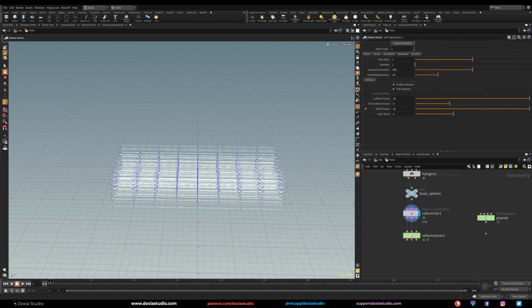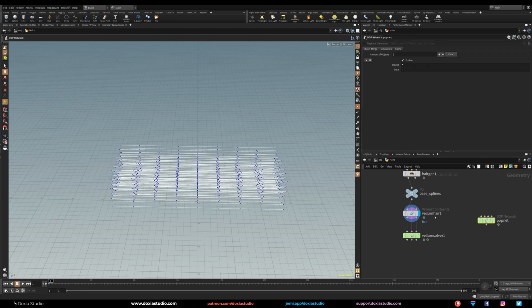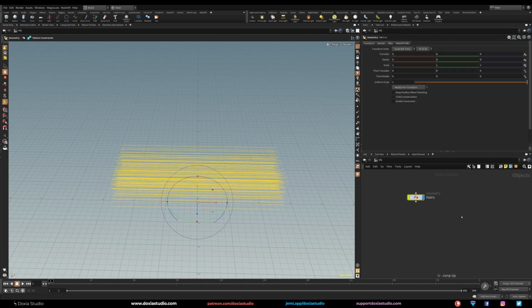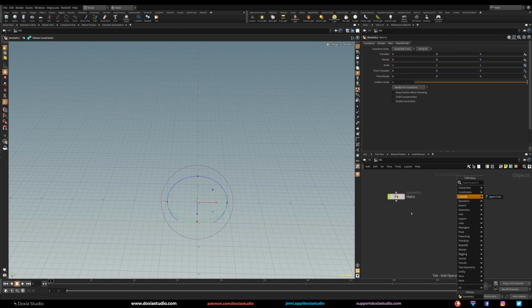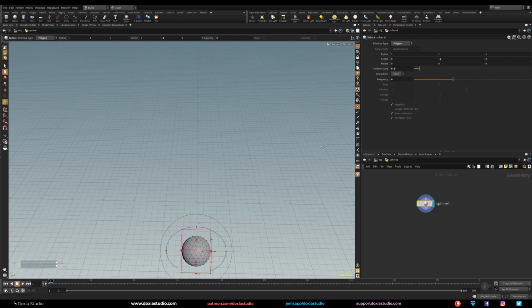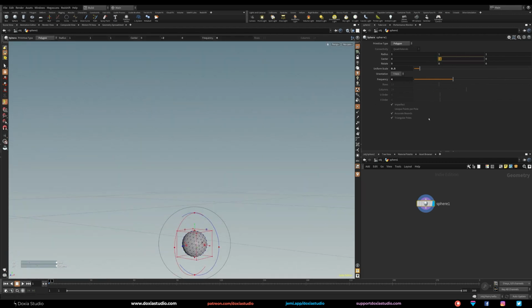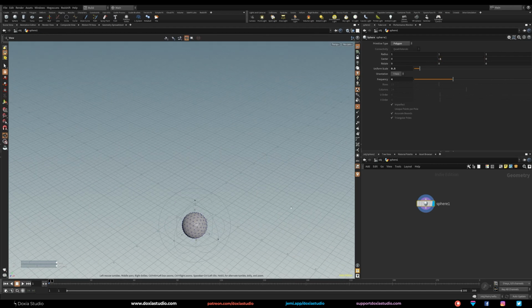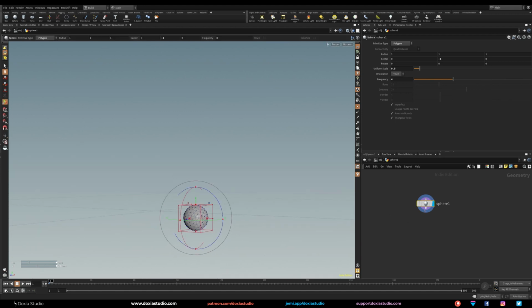So in our case, we are going to use a pyro simulation to affect our hairs, okay? And create this cool and fluid animation. So let's for now go up. Let's turn off our hairs and let's create our pyro simulation. So let's go really quickly. I'm not going to explain that much here because I already covered this in the intro to pyro simulation. Let's lower this down. Let's change to polygon, change the frequency. Let's put this down a little bit. Maybe -1. Because I want this to be below the floor, okay, because we know that our hairs are on top. Okay, let's place a null.